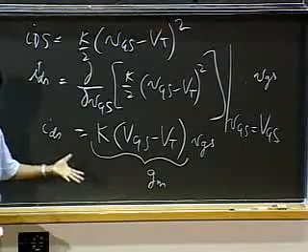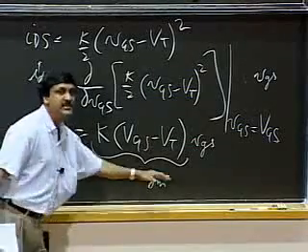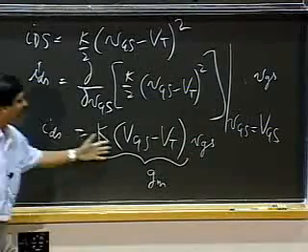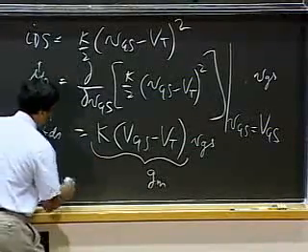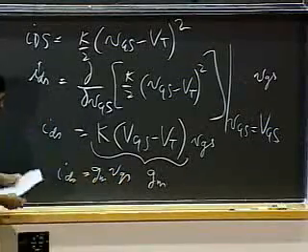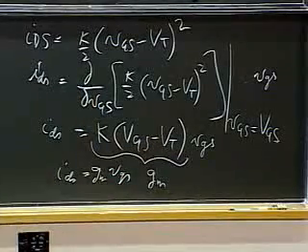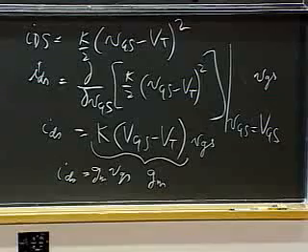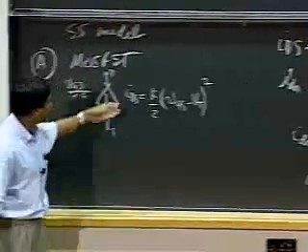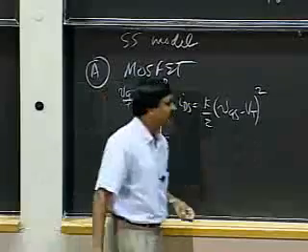So therefore, the small signal model for the MOSFET in saturation, not surprisingly, is a linear voltage-controlled current source according to the following expression. So IDS equals GM VGS. GM is a representation for K times VGS minus VT, and it's called a transconductance. It's called a transconductance because it reflects the conductance properties of this based on the input.